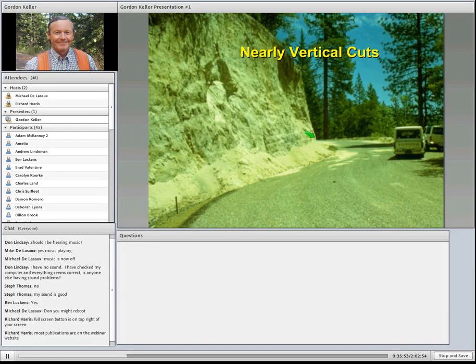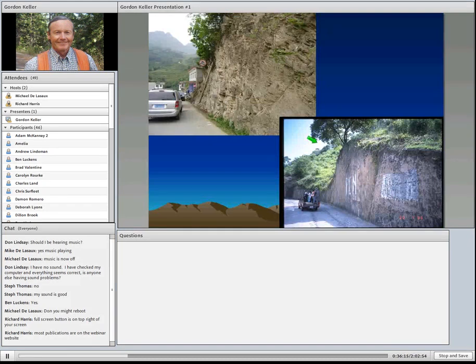But that's a decision you have to make, whether you want to keep it steep, which has some risk of failure in some soils, versus laying it back at a flatter angle, which is more stable from a mass stability standpoint, but more erosive, with more area exposed to erosion. Some things are obvious. If you're in pretty rocky material like this, pretty well cemented ashes like you have a great deal of in some areas, Central America at least, it'll stand just about vertically, and you want to make your cut as steep as stable.